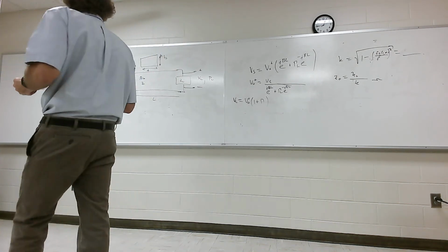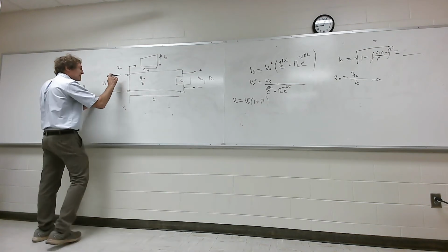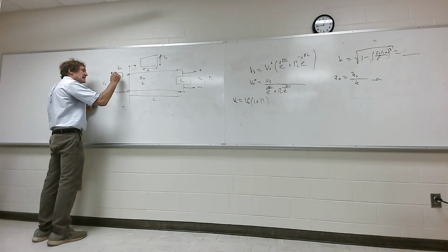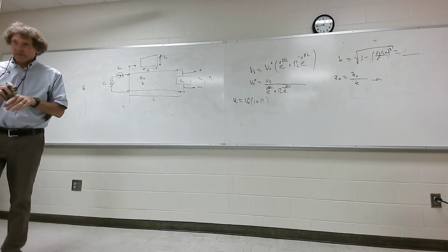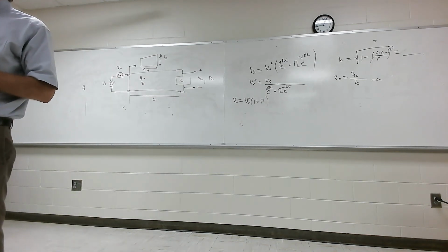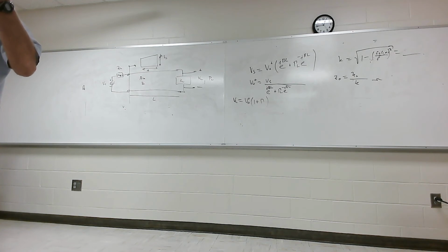And I would definitely also, I didn't have time to do this, but I'd put a Z input right there, a Z source, just so you know how to do the whole problem, including that. But that only changes the value. Then you need the input impedance to get the value of the voltage at the input there. It's not giving us VS.